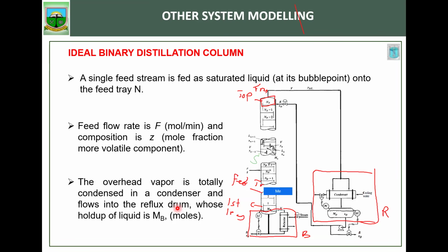third tray. Usually in a distillation column, you don't put the feed at the bottom. You put the feed a little bit higher. And so we have at least a tray that we use. So the feed tray is always above the first tray in the column.